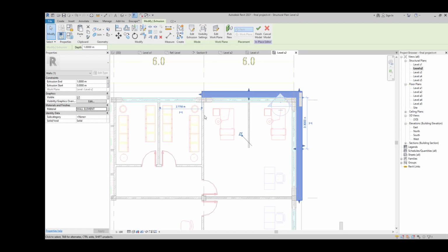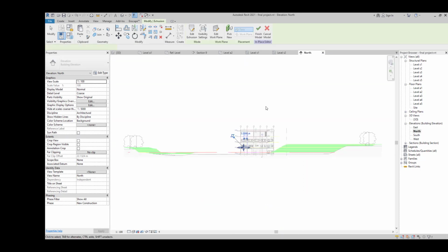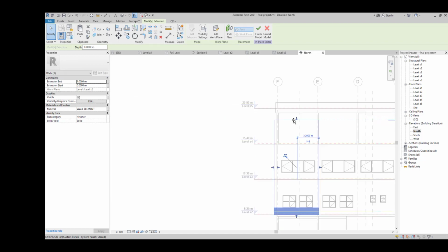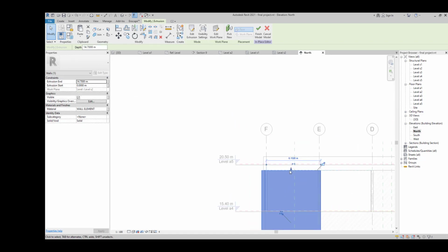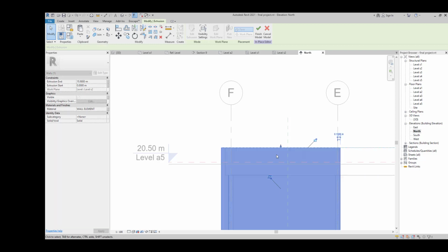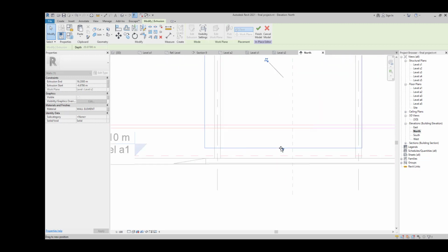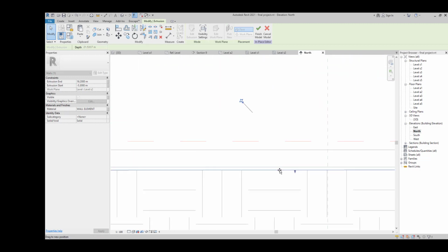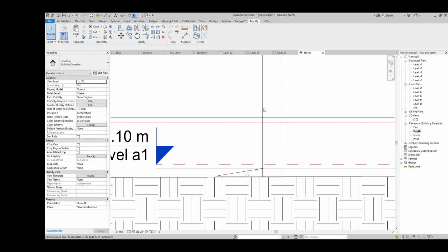So the next step is going to one of the elevation views, or a section. All of them can work because we need to drag our element until we reach our floor or even above our floor, because it's going to be outside of that. And after that I'm going to reach the floor here, like here, and that's it. Just going to finish model.